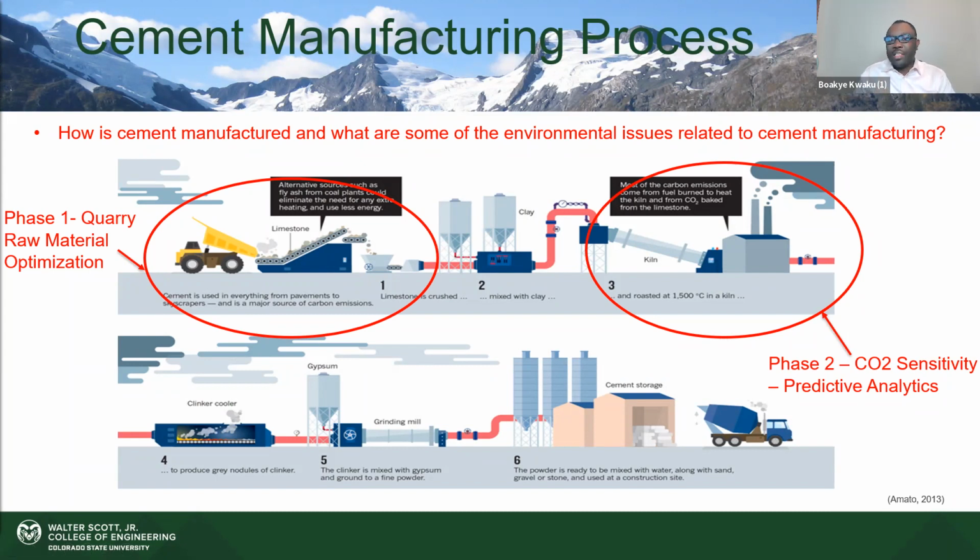Because of the heat, we change calcium carbonate into calcium oxide and CO2. And then the process of calcination continues within the kiln, which is also a high heat zone, about 1400 Fahrenheit. Within the process of heating, it changes in chemistry. And when it changes, the limestone, in combination with aluminum, iron, and silica, becomes a silicate product called clinker.